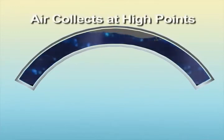Two problems become apparent. The pocket of air accumulating at a high point can result in a line restriction. And like any restriction, the pocket of air increases head loss, extends pumping cycles, and increases energy consumption. The presence of air can also promote corrosion in the pipe and fittings. As air continues to accumulate at the system high points, the fluid's velocity increases as it is forced through a smaller and smaller opening. As the pocket of air grows, one of two things will occur.